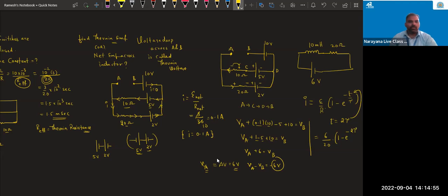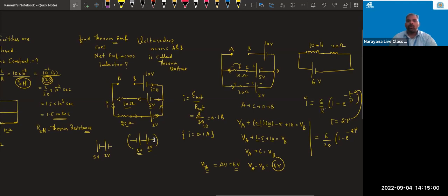Net resistance is 20 by 3. Okay, sorry. Correct. He was correct. So 20 by 3. Yes. Here also 3 will go to the upside. Very good. Tau cancels. So 2 3s are 6, 3 3s are 9, by 10 means what? 0.9 into 1 minus e power minus 2. Is the current after what second? 2 time constants. Okay.